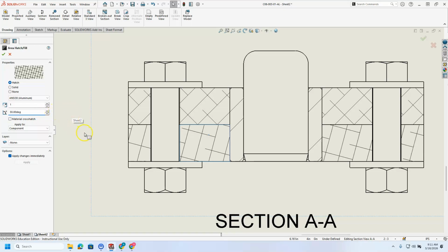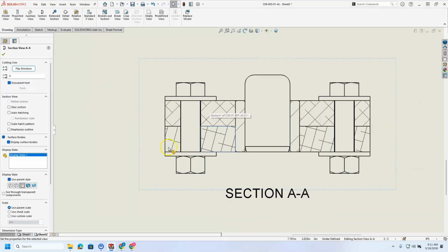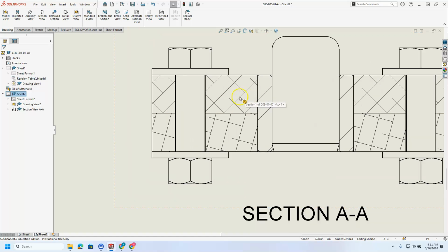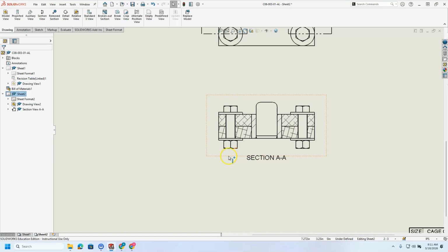Now that is a very distinctly different hatch pattern. I can clearly see that these parts don't line up. And that's what we want. Normally we prefer to do just like a 60 or a 90 degree hatch flip. But in this case we had to go with something a little more in between to get it to not line up. Okay. So our view is in, our section view is correct, and our crosshatch has been adjusted.